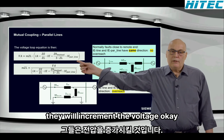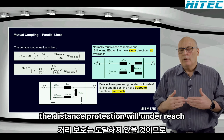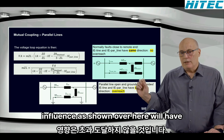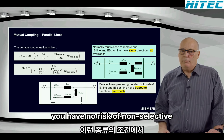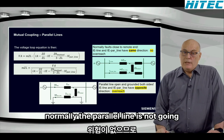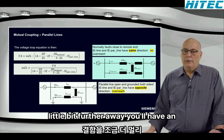they will increment the voltage. Okay, and remember what we did during the first session. If we have incremented voltage, the distance protection will underreach, it will not overreach. So the parallel line influence, as shown over here, will have no overreach. So you have no risk of non-selective tripping under this kind of condition. Normally the parallel line is not going to be a critical thing in terms of overreach. You'll tend to see the fault a little bit further away. You'll have a little bit of underreach.